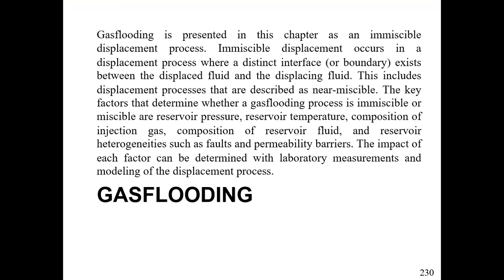So key factors that determine whether the gas flood process is immiscible or miscible are reservoir pressure, reservoir temperature, composition of the injection gas, composition of the reservoir fluid, and then reservoir heterogeneity, such as faults and permeability barriers.